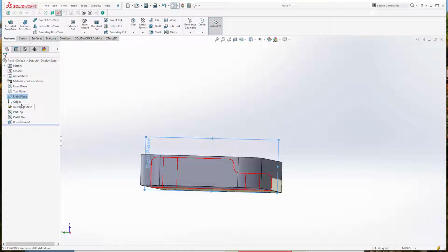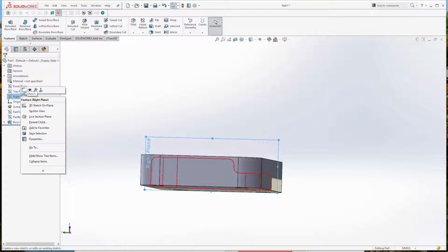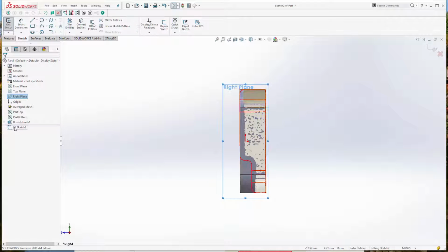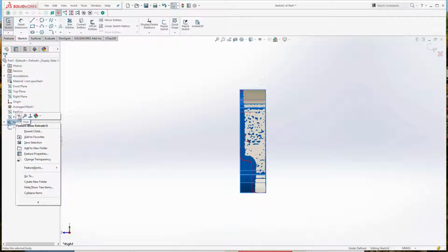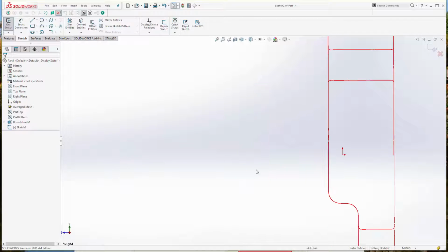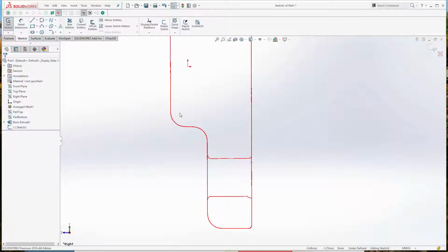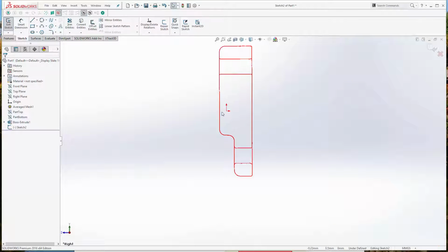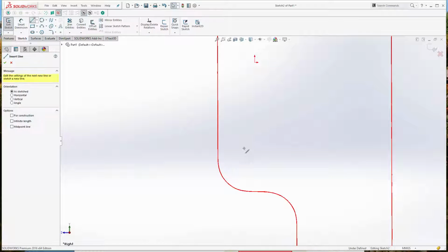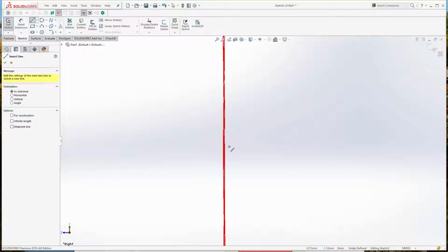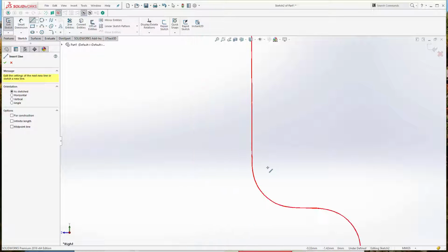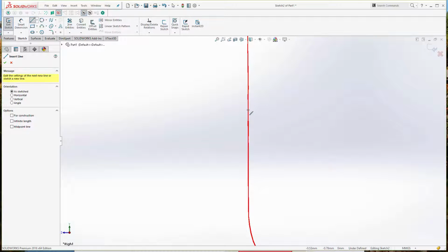I like that. And along my right plane, I'm going to start a new sketch. Just so things are a little bit easier to see, I'm going to hide my solid as well as hiding the mesh. So all I'm looking at is this outline right here. And what I'm going to do is do a sketch where I can use it as essentially a cutout. And the line's extra thick because it's actually an average of all those slices that I took from earlier.